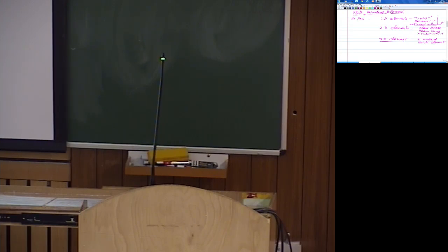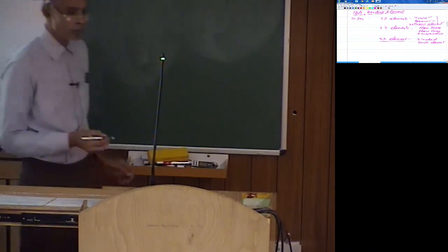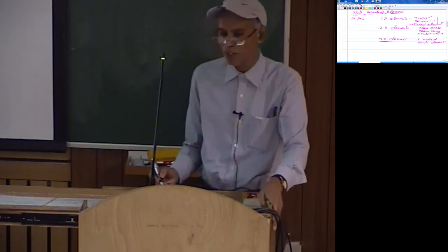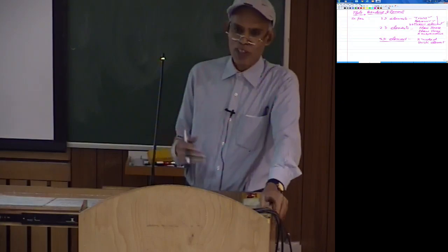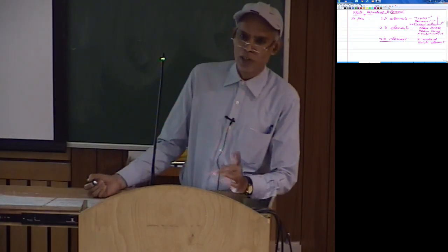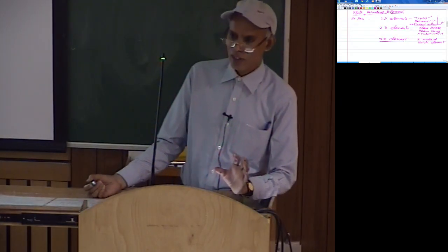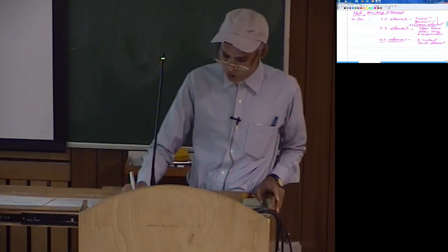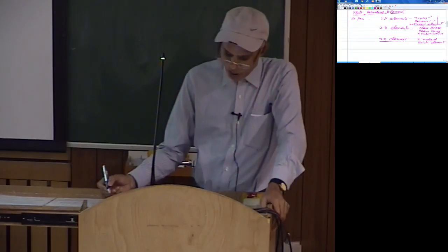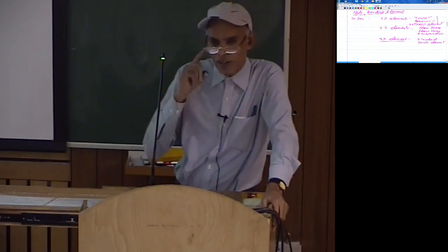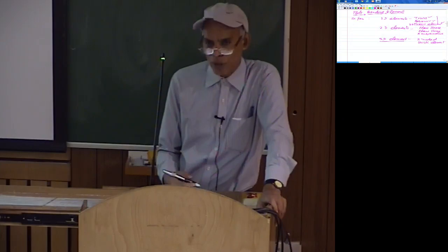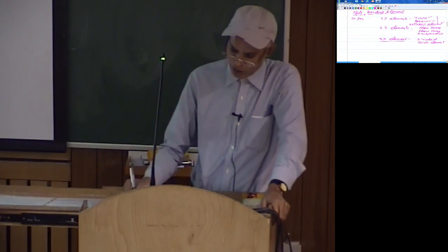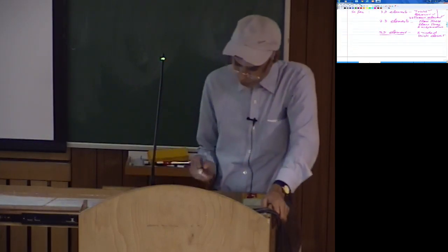To maintain the same aspect ratio, you have to have a large number of elements in the other two directions. So computationally, the use of 3D solid elements might be more involved, just because we have to maintain a certain aspect ratio of the element sides. Because of that, sometimes we prefer to use 2D elements, and 1D elements are of course computationally even more efficient, but then you have to see whether these assumptions are applicable or not.